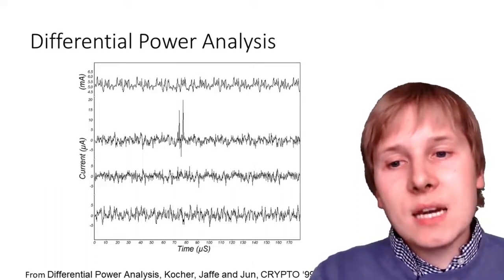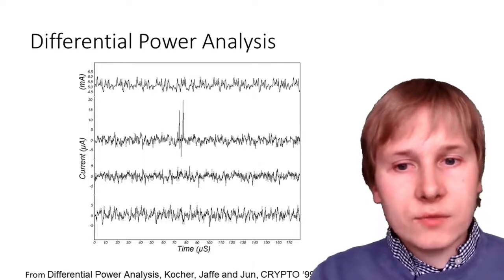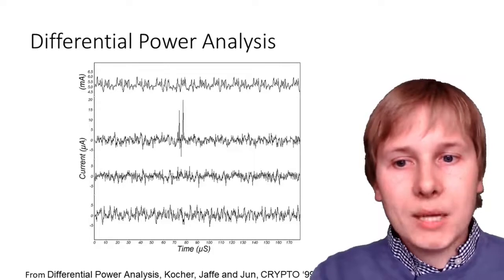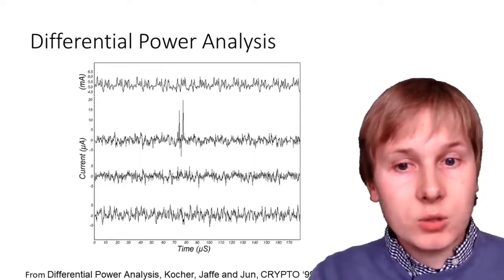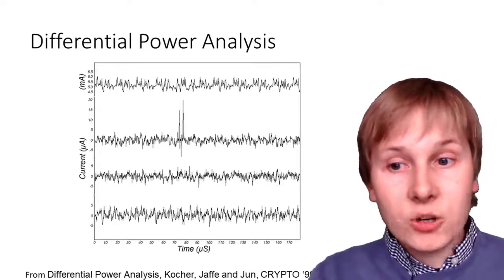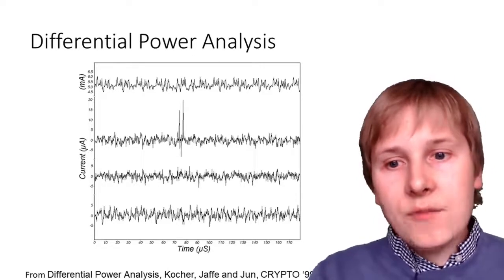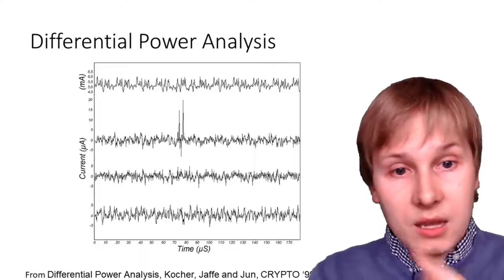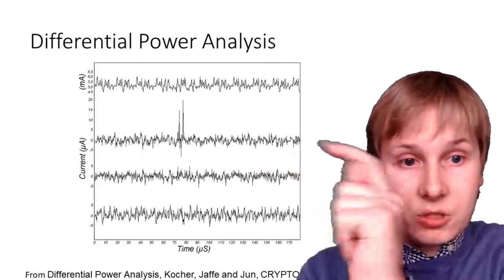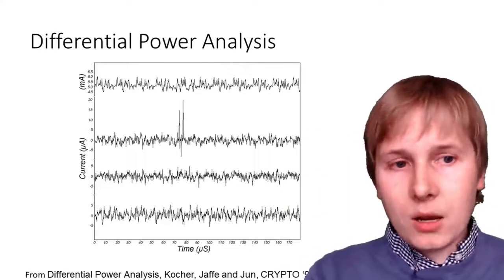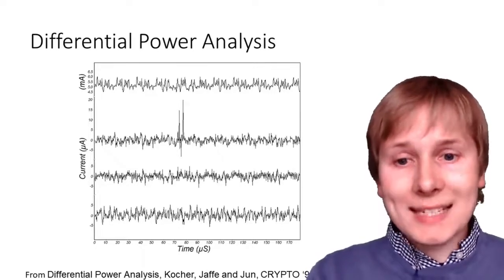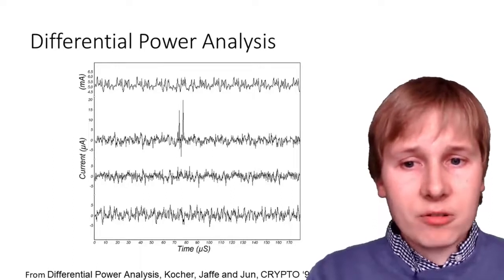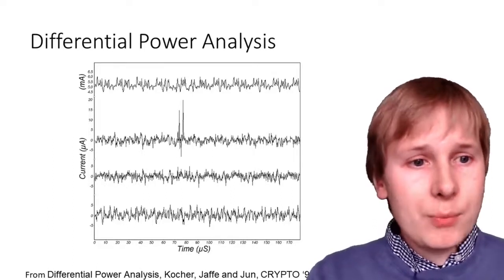The basic idea of this trick is that you collect lots of traces of different ciphertext encryption traces and try to group them together based on which you think should feature the same computation on the same data based on your guess of a small bit of the key. If your guess is correct, then you'll get correlation and a notable spike, like the one in the example on screen, just over there, by comparing your two results. If your guess is wrong, you'll get no such spike, so you'll try a different value until you find the correct one, then move on to do the same with the next part of the key.